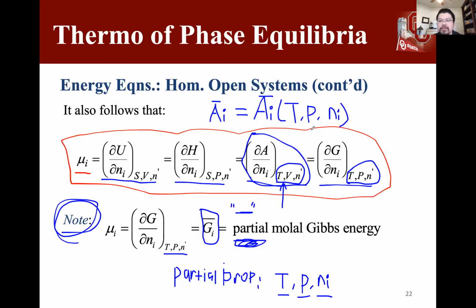Okay? So that is very similar to the most recent discussion. You see that we try to have the enthalpy H as a function of T and P. Although the enthalpy itself, by the pristine definition, is a function of entropy and pressure, with the help of math we can derive the equation, and we manually put the entropy as a function of temperature and pressure.